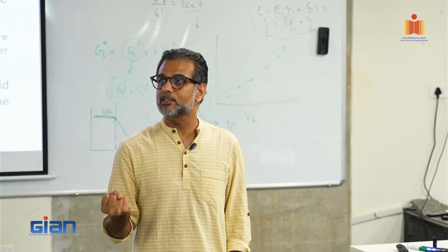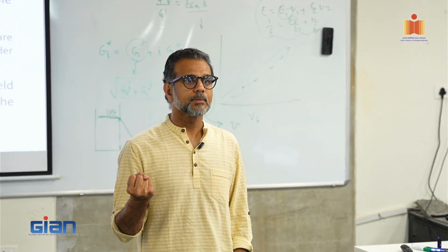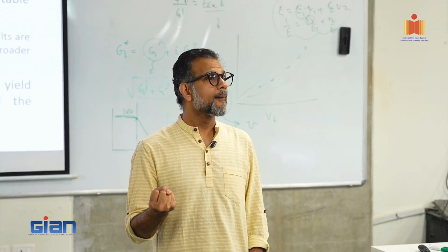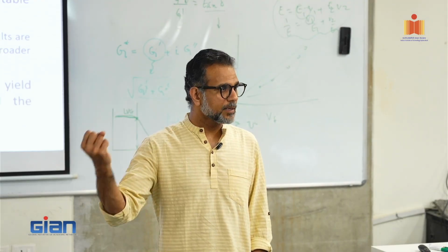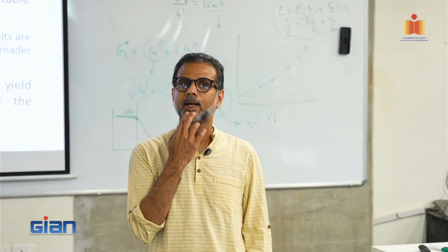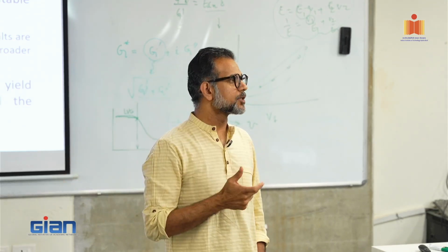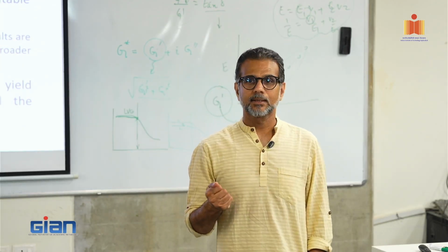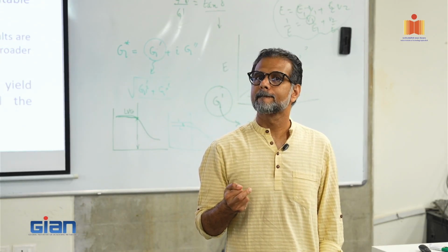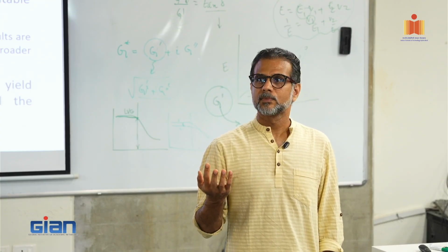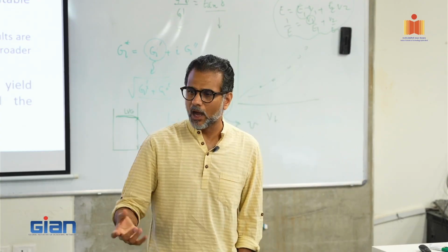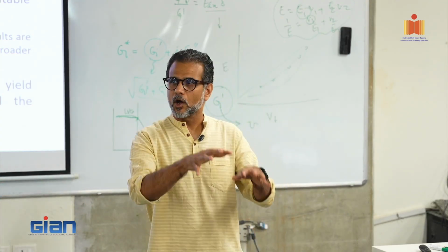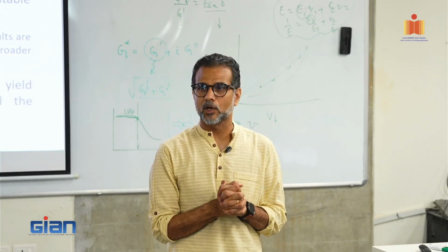Thixotropy, I forgot that. What will thixotropy tell you? The ability to break and regain, rebuilding kinetics. And thixotropy can be connected to yield stress as well, because you can measure it through yield stress. What else? That's it. Structuration rate, which is again how quickly the strength will develop, which can be related to storage modulus as well. So those are all the general rheological characteristics that we talked about.